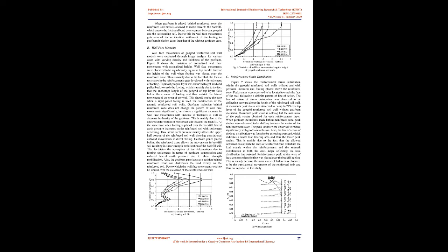The strong box was proof tested for its capacity before the beginning of the tests for different soil backfills and different loading intensities. No deformations were observed in the steel panels of the strong box until the loading intensity reached 55 kN. However, as the vertical load reached 55 kN, the characteristic value for 95% successful cases, the front glass panel was observed to break catastrophically. A number of thin polythene sheet strips were placed inside the strong box after application of a grease layer.